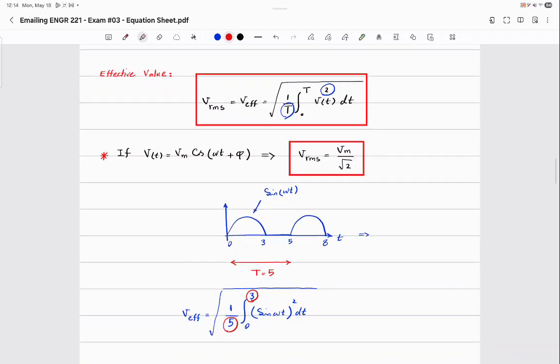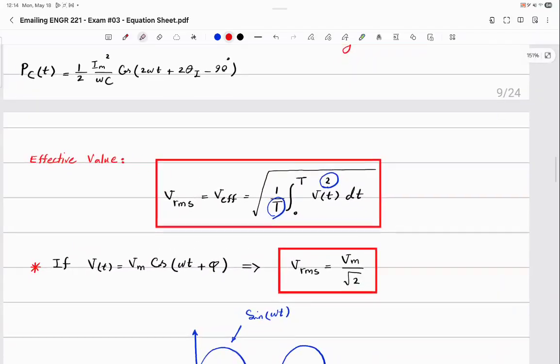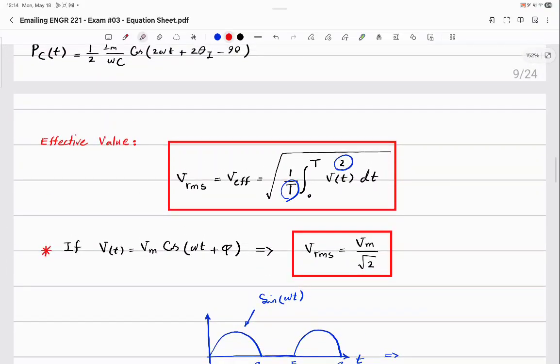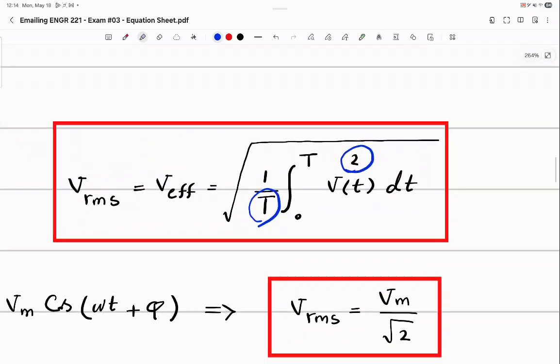The effective value: a couple of important things. First of all is recognizing what the period is in your problem, so you can substitute T with it here. The second one is that sometimes you forget it should be a squared version of the voltage or signal, whatever that is. The third important thing to remember is do not use the area. You can't. Why?